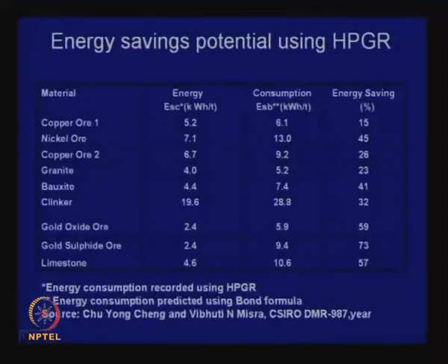Generally, the crushers are fixed, but in this case the crushers press onto the particles which are going through the space where they are being ground. That is why, and they are under high pressure, they are called high pressure grinding rolls.